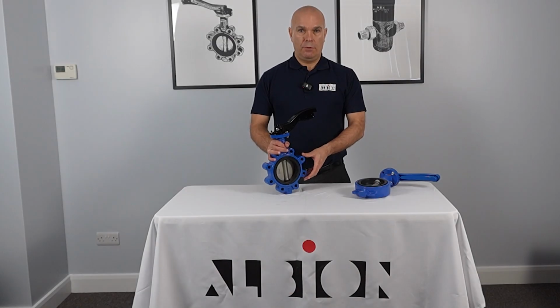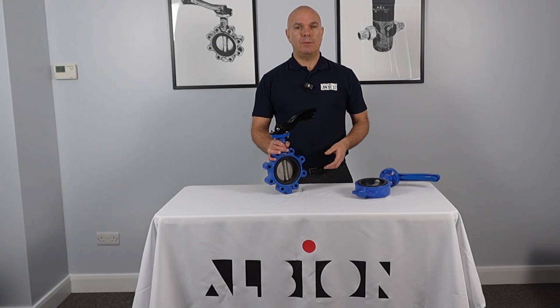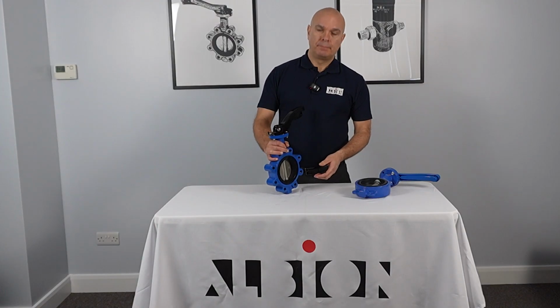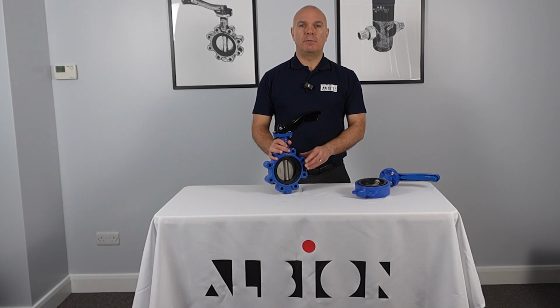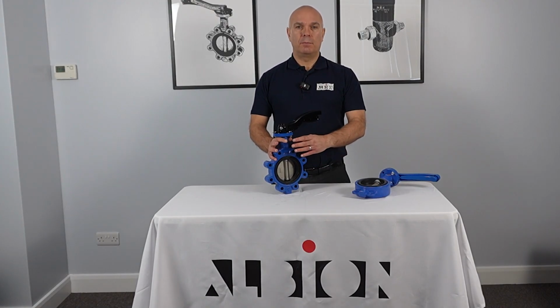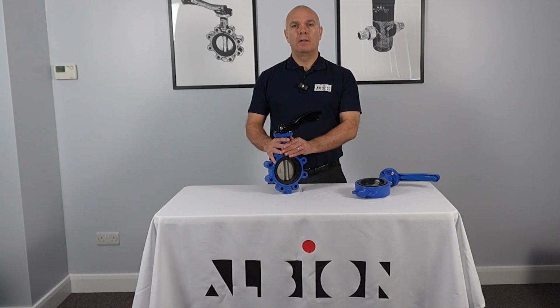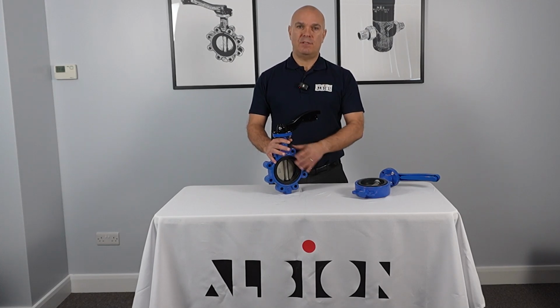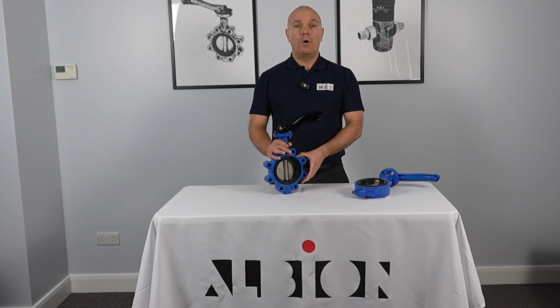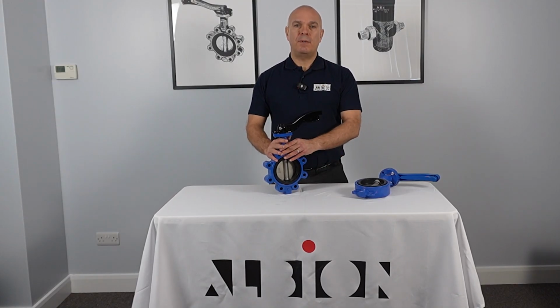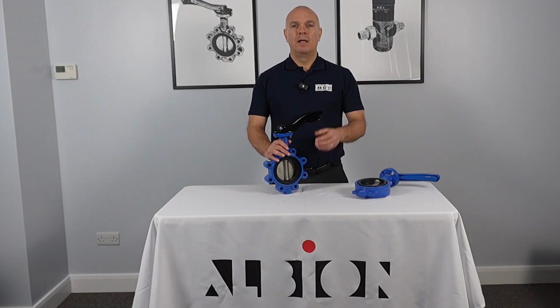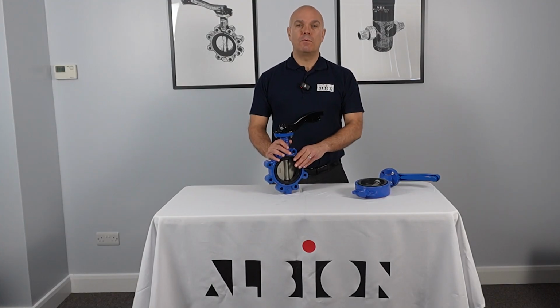There are also some other components within a butterfly valve that you can't see, such as upper and lower shafts, which connect the lever and the top of the valve and in turn drive the disc when a torque is applied. There are a couple of seals in the stem which prevent any media leaking to atmosphere. Ordinarily, these parts do not come into contact with any media. There is a cotter pin which acts as a fastener device and a circlip which prevents any movement of the components of the butterfly valve.